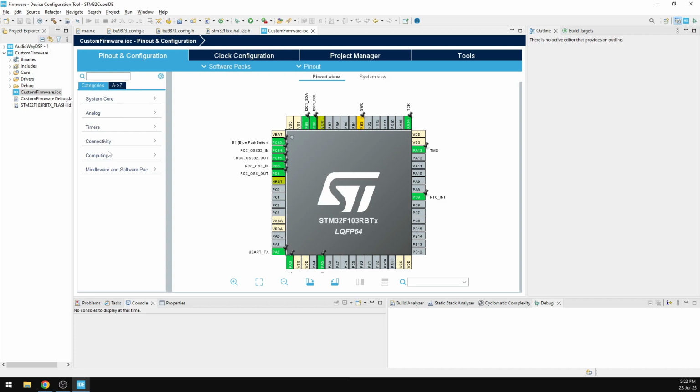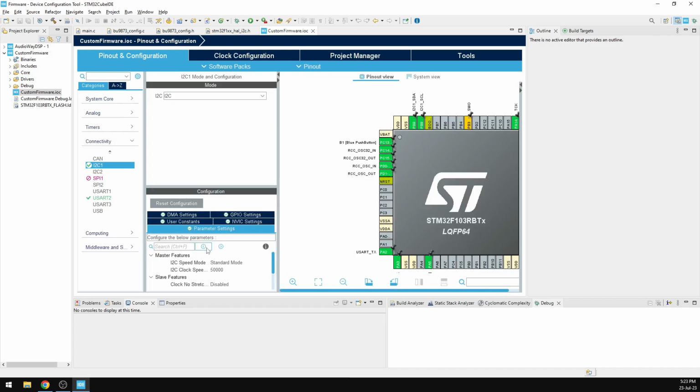And as I said, in the datasheet, at the power rating function, you might need to check those settings because you might have a clock speed that is faster than appropriate, and you have to do the fine adjustment to those settings. But in this case, I put it at 50 kilohertz clock speed, which is fine.